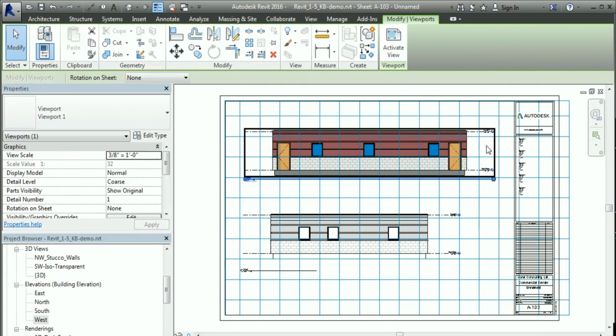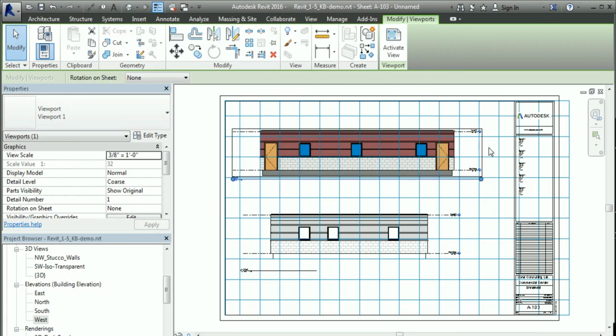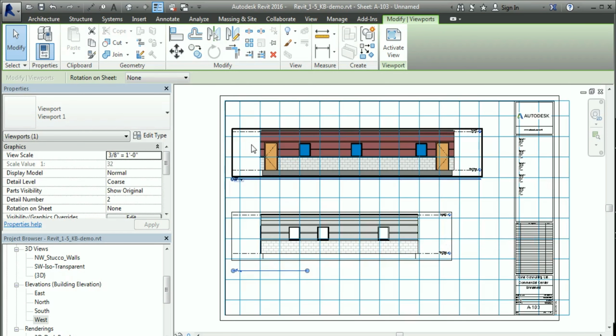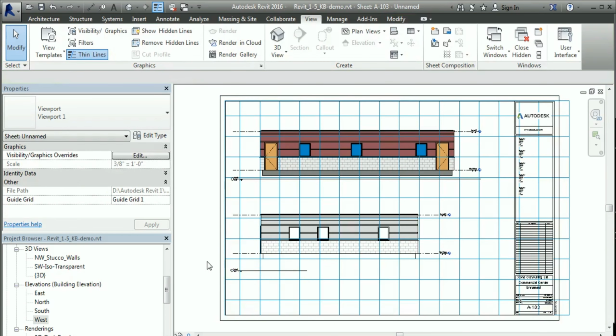And then I can pick this view, and I can move it over, and the wall on the other sheet was in line with grid line number 2. And this one was also in line with grid line number 2. And by referencing the number of squares in or the number of squares up, you can match up a series of views so that when you turn through your sheets from sheet A1 to sheet A2, the elevations will appear